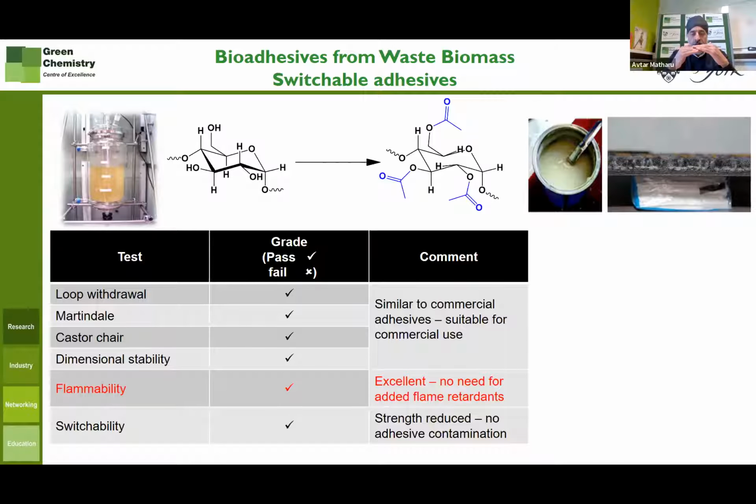When it comes to end of life, we take the carpet, we put it into a tumble dryer set at 130 degrees centigrade, approximately 30% relative humidity. Under those conditions, the glue debonds. It switches from bonding to non-bonding, which means that the face fibre goes one way and the base layer goes the other way. Both are washed, re-yarned, and then brought back together.